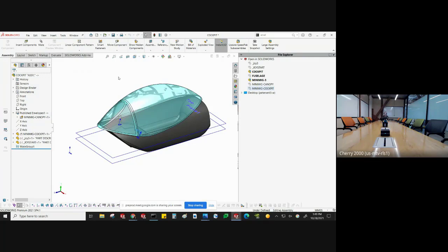I also don't have to worry about, did I accidentally make this thing in the bill of materials, or am I weighing it when I do my mass properties? So it's just an easier way to use an existing tool. It is one of those tools not a lot of people are familiar with, but it's a really nice assembly creation tool. When you're in the design process, I use these a lot just because I have a reference that everything's using and I don't have to worry about whether I've got duplicate parts.